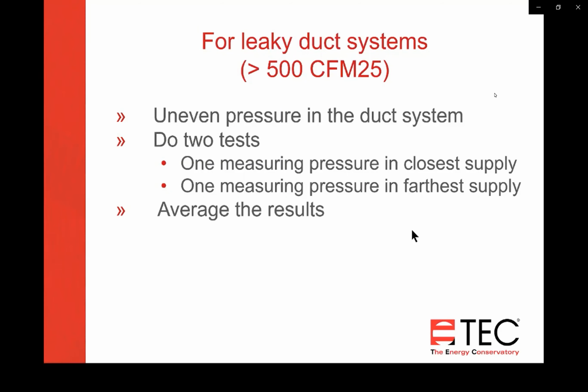Like I mentioned previously, the total airflow is based on where the leak is, how big the leak is, and what the pressure is across the leak. And if you've got different pressures across all of the leaks, you get some kind of funky numbers. So measuring at the farthest and the closest and averaging the results is the best option.